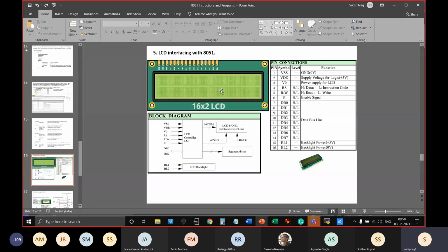If you come across any display device, it comes in 2 parts. What are the 2 parts? The parts are basically the LCD panel and its controller driver circuitry combined together. I'll combine the driver and controller together, and the panel part. All we are seeing from outside is the panel part, but every panel must have a controller and a driver.